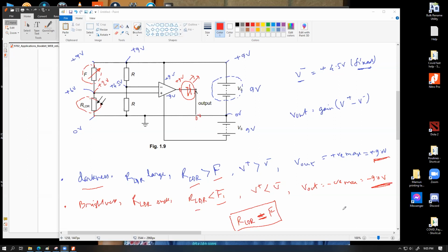The way a transistor works is that with the presence of a significantly large amount of base current, it opens up the collector emitter pathway large enough so that significant current can flow by, and any electrical appliance that is connected in that branch will start to work. You will have a proportional ratio between the base current and the collector emitter current. That's how it works. For the transistor, you can have a device working or not working based upon the presence of the base current.